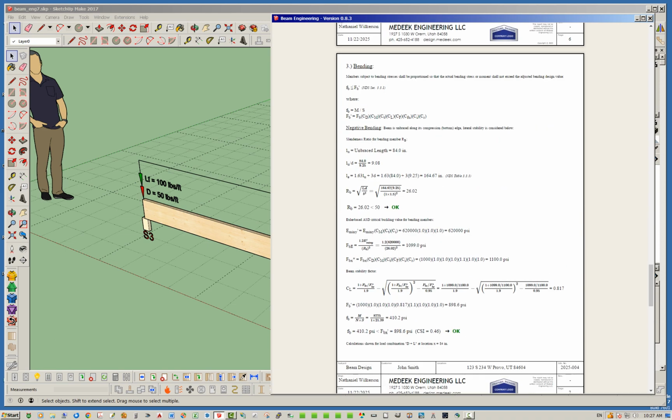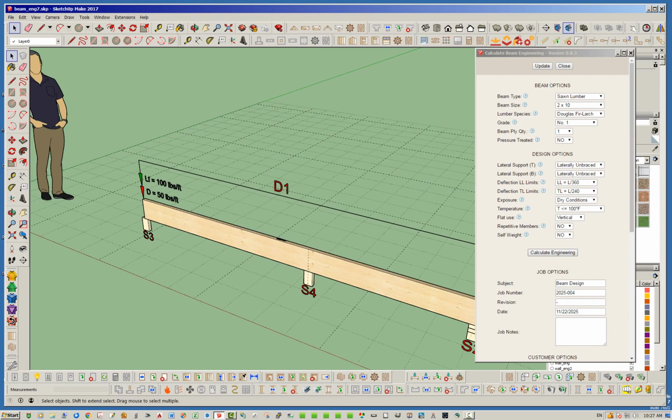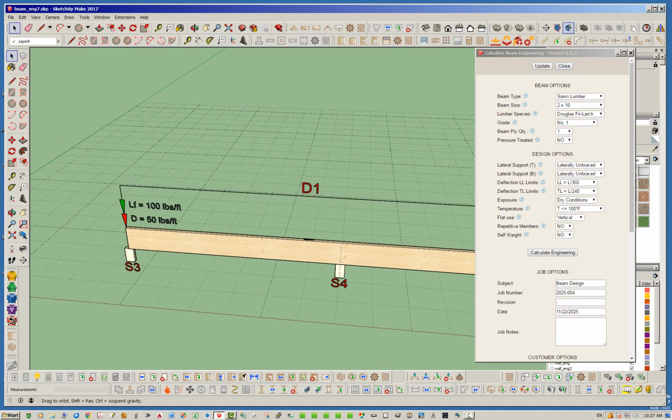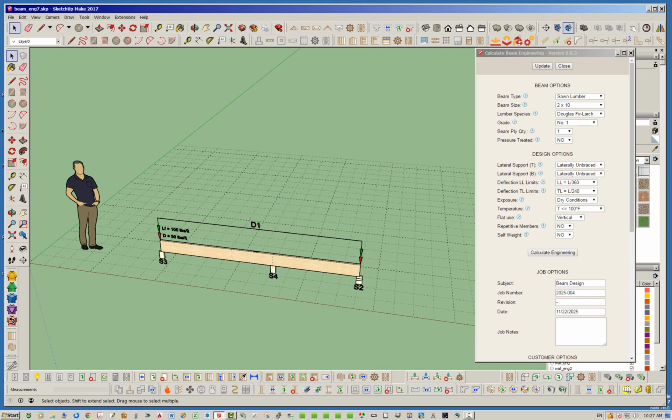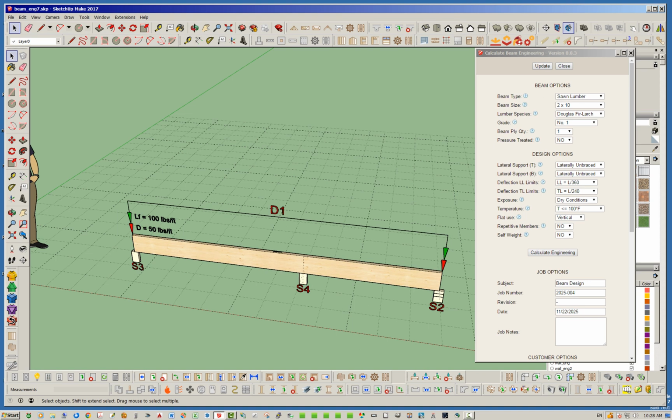Right now this particular example is a little overly simplistic, but let's say that you have multiple supports and you want to have lateral bracing specifically along this support, but maybe it's laterally unbraced at the bottom on these other 2 supports over here somewhere. So you can mix and match and get the bracing. It gives you enough flexibility, I think, to fine-tune the bracing to what exactly you need for your specific situation.